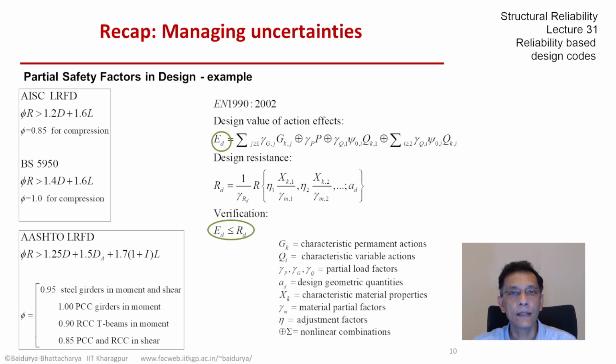Now, as we said in the previous slide, let's see how Structural Eurocodes, being one of the latest and being very comprehensive, approaches the design process, and as I said, it's reliability based. So what it tries to cover, what its expectations are, at least at the high level. So the next few slides, I'm going to go through the first 3 or so chapters from EN 1990 and pick out the important points or the important phrases that bring out the philosophy and the expectations of the Structural Eurocodes.